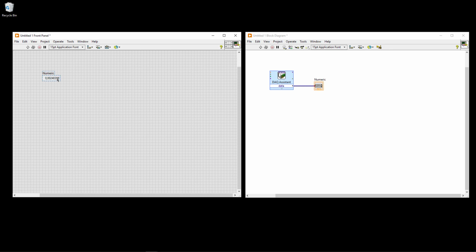So give me a few seconds so I can connect the battery, and then I will just run my application once more. And then you see I'm able to read 1.3 volts from my battery on this analog input channel number 0. So this is the most basic way to communicate and program your DAQ device in LabVIEW using this DAQ assistant.